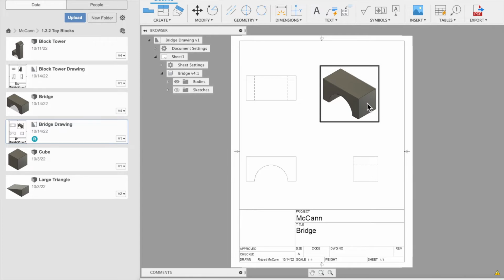So if I'm doing this, I say, okay, for feature 1, I see I have this hole taken out of the center. So I'm going to have to make sure I dimension the hole. That's the location, horizontal and up and down, and then also the diameter. And then I'm going to have to dimension the object, the entire rectangle. Those are the only 2 features I have.